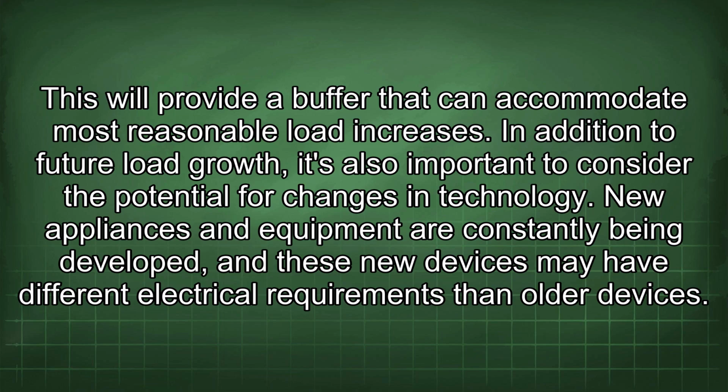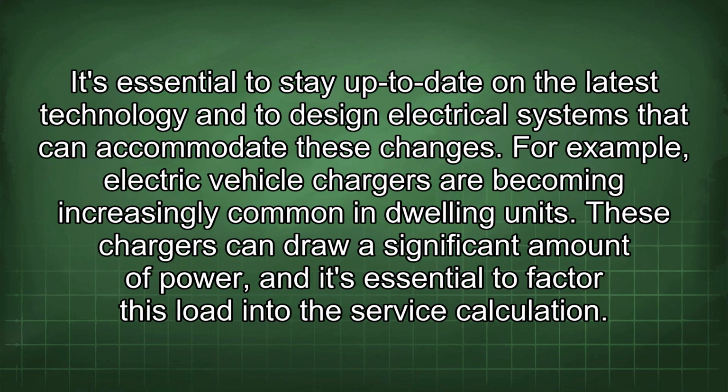This will provide a buffer that can accommodate most reasonable load increases. In addition to future load growth, it's also important to consider the potential for changes in technology. New appliances and equipment are constantly being developed, and these new devices may have different electrical requirements than older devices. It's essential to stay up to date on the latest technology and to design electrical systems that can accommodate these changes.